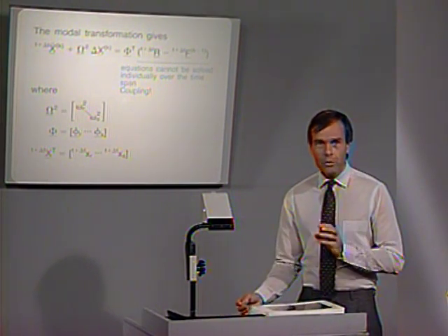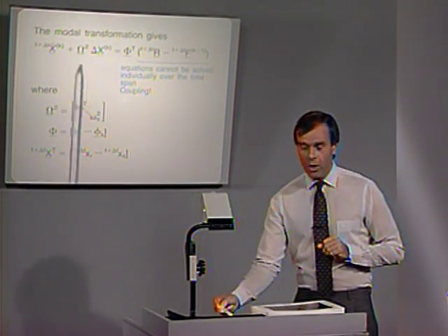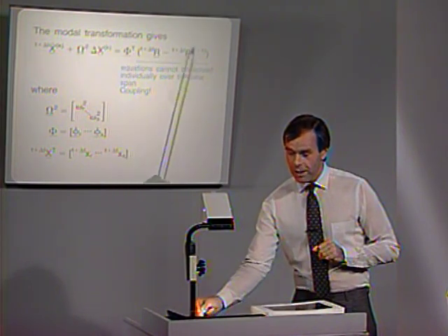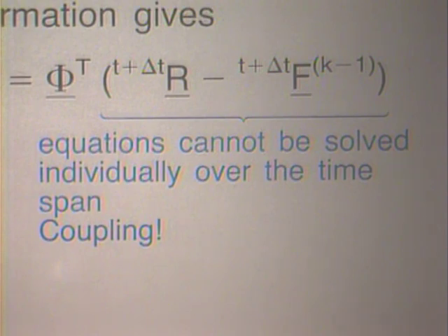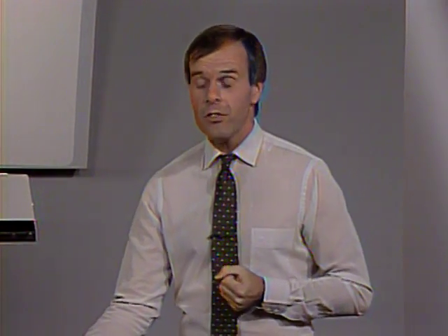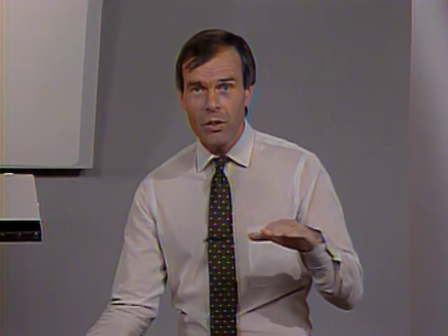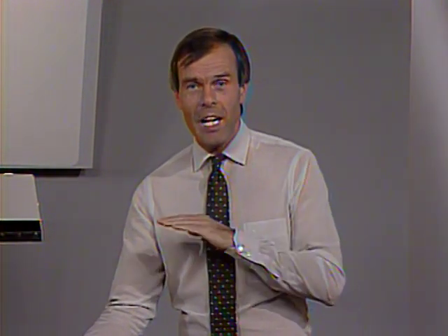An interesting and most important point is that in nonlinear analysis we have a coupling, due to this vector appearing in here, between the different mode shape equations or modal equations. We cannot solve, as we usually do in linear analysis, one equation of the mode superposition after the other.